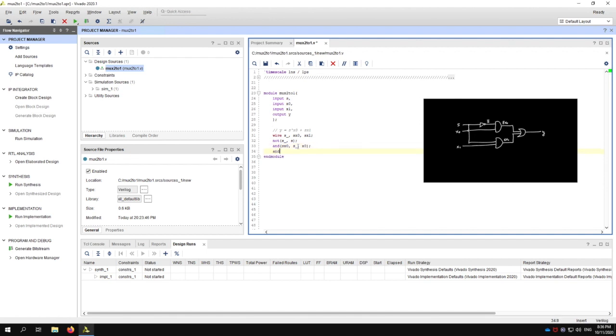And then similarly, I need a second AND gate. My second AND gate has as output this signal that I called SX1. It is going to have two inputs: my top level input S and my top level input X1. And then finally, I have an OR gate. The output of my OR gate is simply my output Y. And the inputs to my OR gate are these two signals, SX0 and SX1.